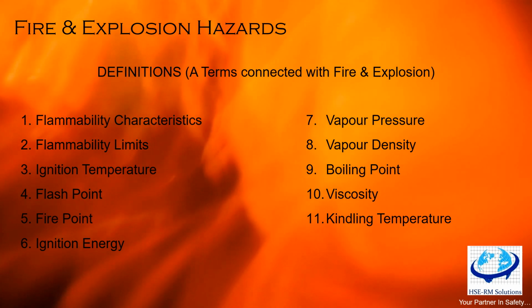The very first term is flammability characteristics. Flammability of a liquid varies with the rate at which it vaporizes, and it greatly depends on the vapor pressure. Vaporization increases with the rise in temperature, and a flammable liquid at an elevated temperature is more hazardous than the same liquid at normal temperature.